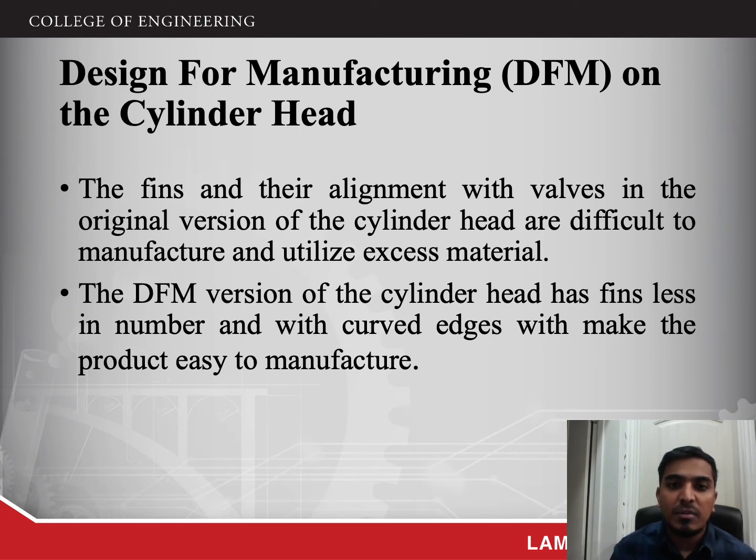Design for manufacturing on the cylinder head. The fins and their alignment with valves in the original version of the cylinder head are difficult to manufacture and utilize excess material. The DFM version of the cylinder head has fewer fins with curved edges, which make the product easy to manufacture.